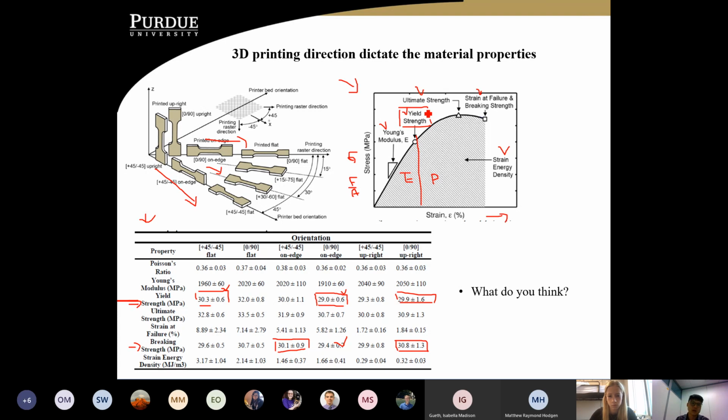You have a constant thing that you are giving a load on it, if that makes sense to you. It is not a concern if today you're applying a load that's lower than 75% of your yield strength. So check the material that you're currently using, Google and check your yield strength, and times 75%. That's the barrier.